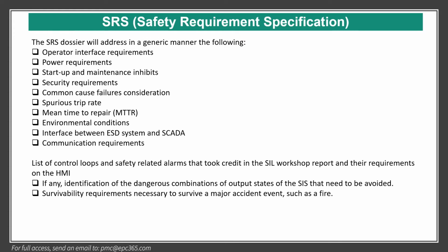Here also there are certain other things: operator interface requirement, startup and maintenance inhibit, security requirement, common cause failure consideration is very important, especially trip rate, mean time to repair, environmental condition and interface between SIS and SCADA if there is communication requirement.